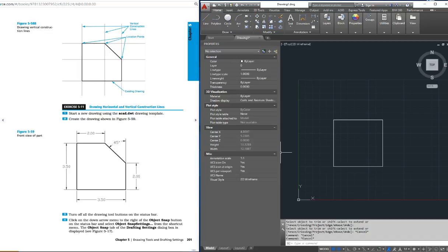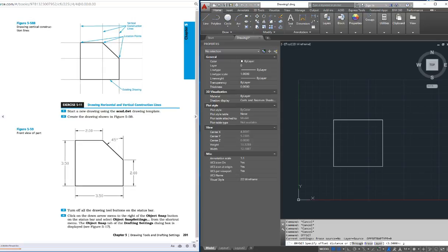So a little bit outside of the directions, I'm just going to use the offset command. And you'll notice it's kind of the same as when I did it inside the X line command, except this time I used offset all by itself. And I'm going to say 2, because it says right there 2, and it says right there 2. So I'm going to come over here, offset 2, enter. I'm going to click, click.